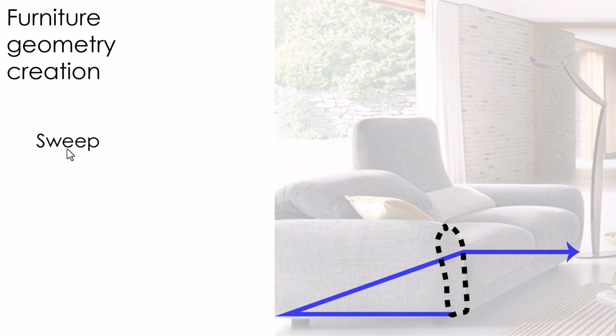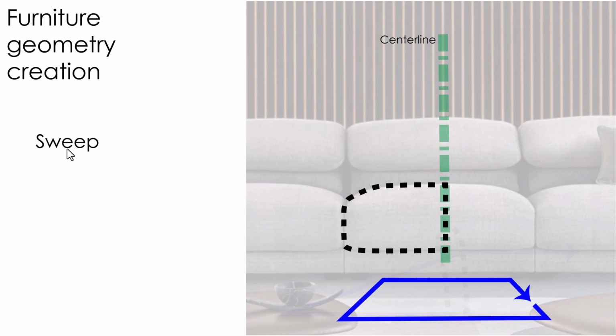Even something that's bulbous, like a couch. Now, I'm not going to pretend to model the folding open part. You can't really animate objects in Revit. But I could easily create the base for this couch by drawing, again, that interesting bulbous profile, and then just creating a path that is the shape of the couch. The bulbous shape will sweep along that path. Now, it will need to be cleaned up to soften the edges, but immediately you can create that nice shape.